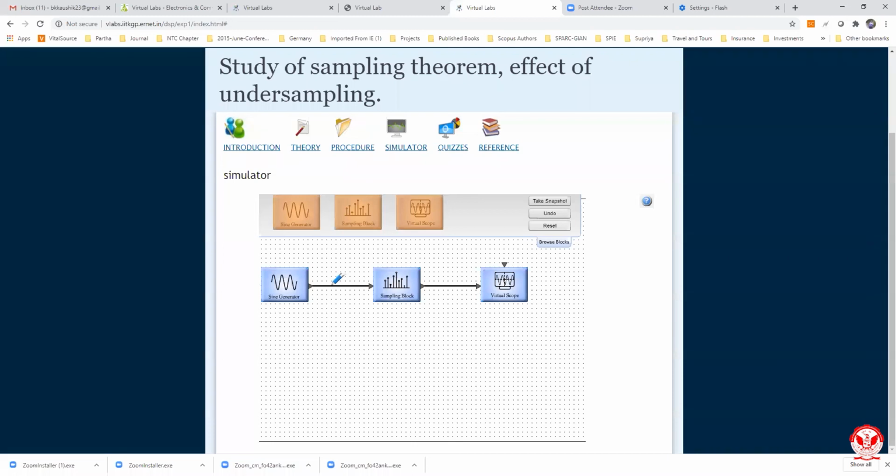So we click here and go up in this manner. Again click here. This line becomes red. Why is this red? Because it has one end connected and the second end is floating. That's why this becomes red. Now we proceed further. Again we click here. Again we get the connection in red color. The red color connection indicates that one end is still floating.